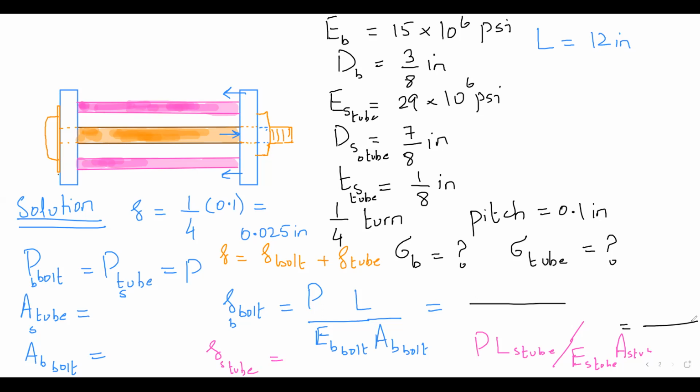So when you turn it a quarter of a circle, a delta deflection will happen, a quarter of 0.1 inches. Because when you have a pitch of 0.1 inches, this means with one turn, this fellow can move 0.1 inches. But the question says that there is a 1/4 full turn. So 0.25 or 1/4 of 0.1 inches. There will be a deflection.